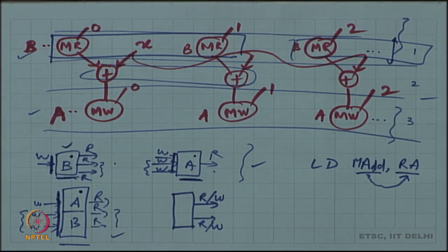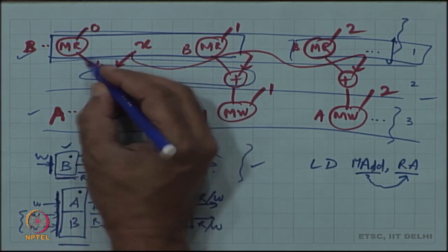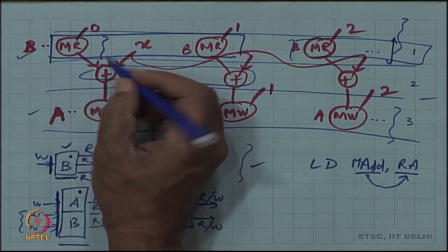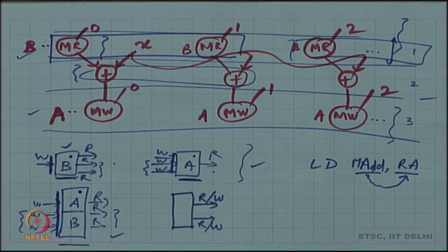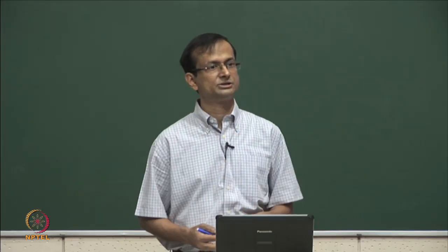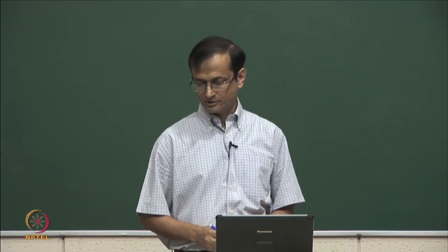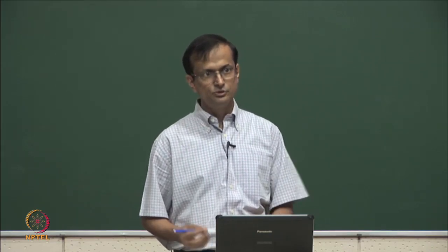Here we do not say where it goes into, but what is the implication when I do this schedule, where does the data go into? Goes in some register. Yeah, it may go into a register, which is implied from the fact that this operation takes place in one clock cycle and the result is used in a different clock cycle. A separate register is inferred, but that inference is just like any other computation. When you have an edge that is crossing a clock cycle boundary, a register is inferred. You do not say anything.